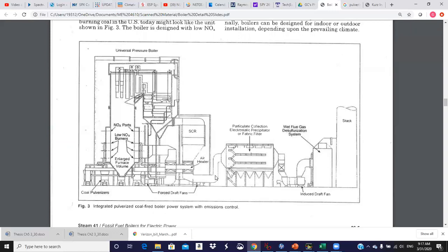All of those ash particles in the flue gas go through that fan and erode those fan blades. And just about every year they have to tear those fans down, and they put ceramic coatings, or not coatings, but ceramic little tile that they put on those fan blades in order to keep them from being eaten alive. And they still have to replace the wheels every 2 or 3 years if they get much runtime on them.